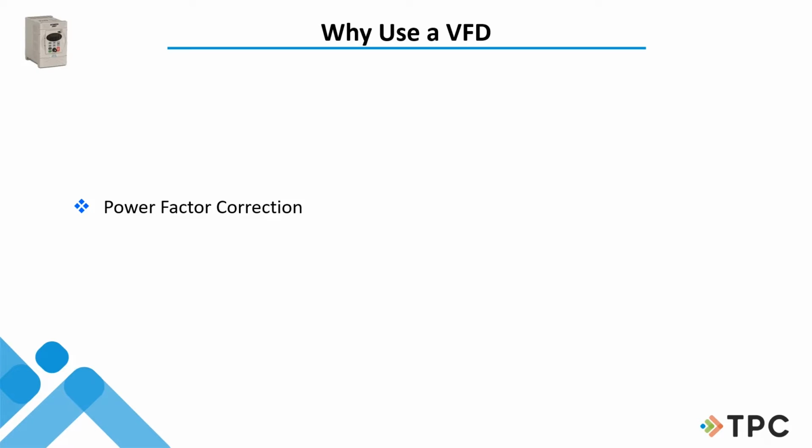And so it's kind of nice to know, when I first put it in, what did my frequencies look like? Were there disturbances or not? And so with a VFD, yeah, I can help my power factor. And everybody knows you want it up in the 80s or 90s. And when it gets below that, the utility usually charges you money because your power factor is too low.